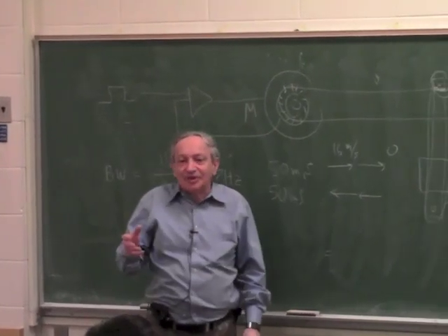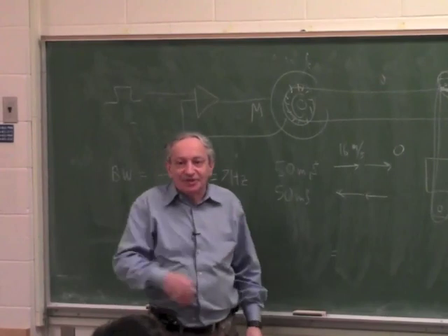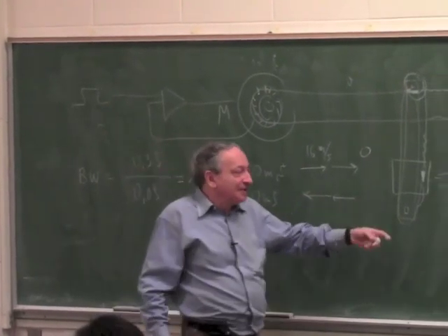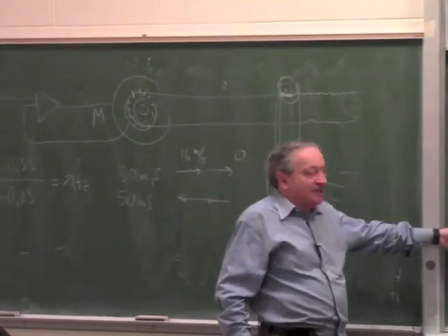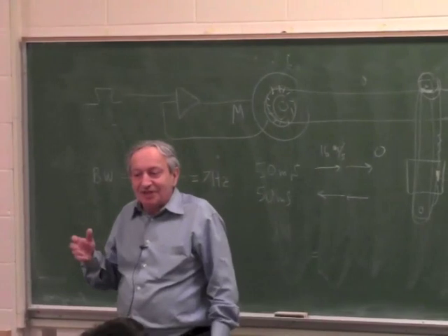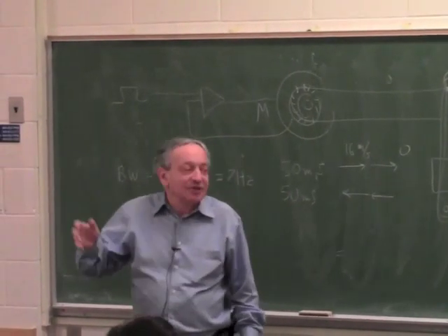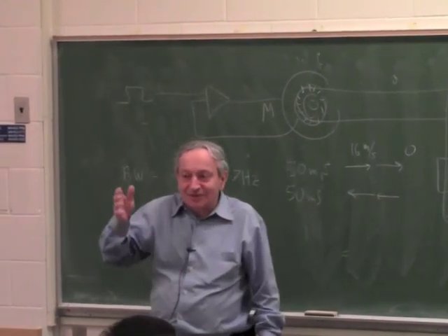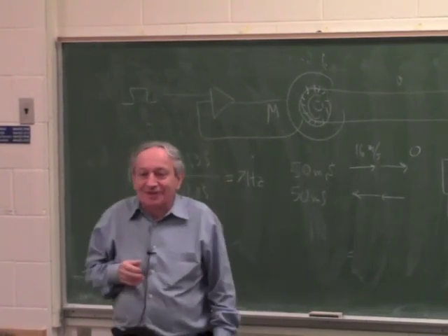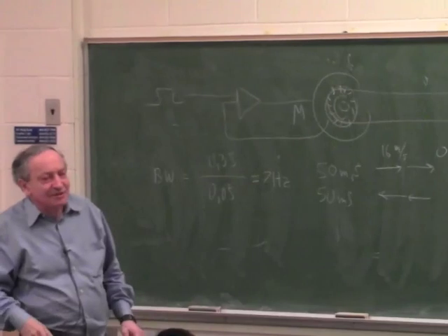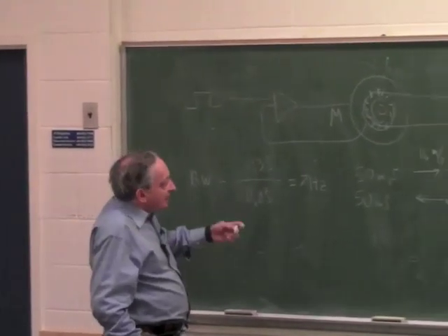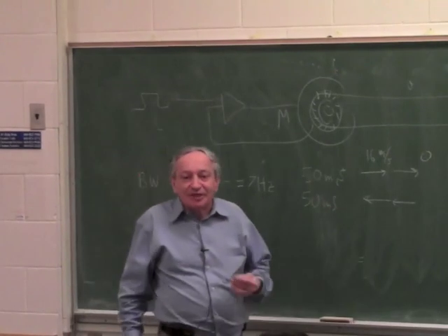If it was a stepper, you wouldn't need the shaft encoder, but a stepper cannot provide such powers. So we're talking here about, even at 10% of the energy, hundreds of watts, right? Because without that, it was 2500 joule times 2.5, right? Was 6 kilowatt. Okay, but if I didn't make any mistake here, sounds a bit high, 6 kilowatt. But anyway, it was many watts. But even with regenerative braking, we're talking about hundreds of watts.